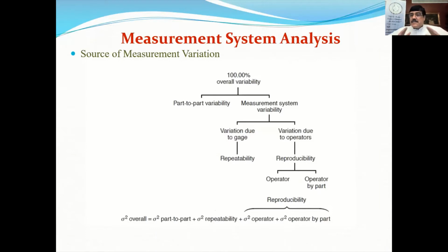And unless you make sure that your measurement system is a good system, then whatever data you feed into the analysis when you go to the analyze phase is basically garbage in, garbage out. This is why you want to understand this concept first. After you understand the concept, all you need is to take the data, plug them into a software, and the software will do the rest for you. It will tell you how much part-to-part variability, how much repeatability, how much reproducibility. But understanding this will tell you where to look when you have measurement system problems, basically.